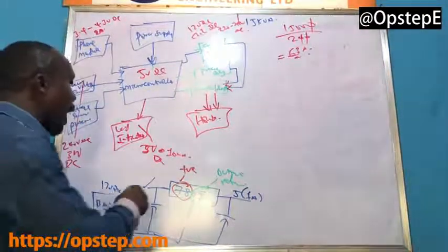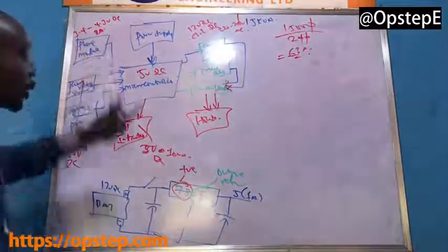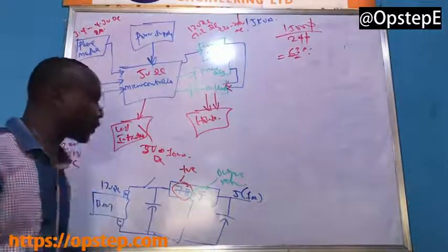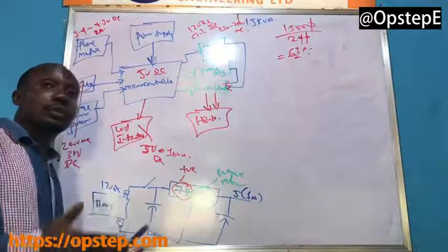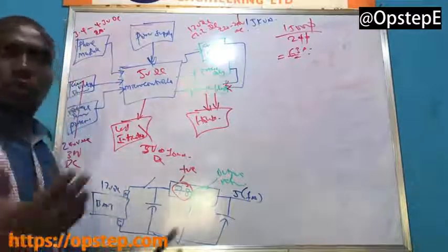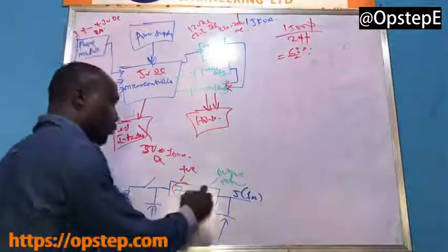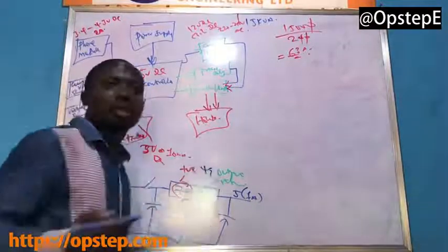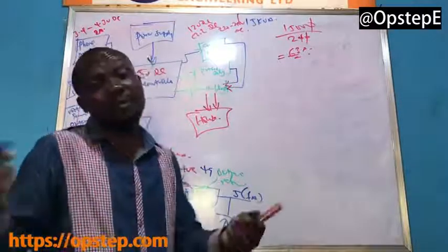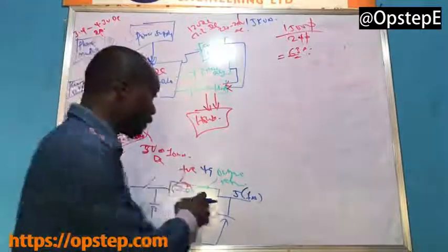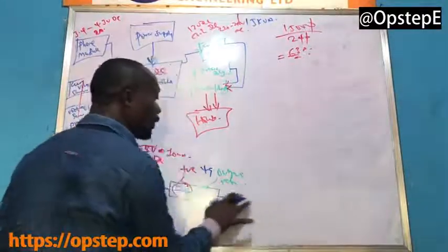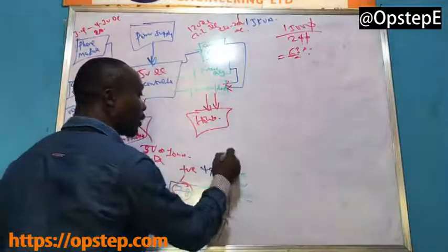Now, how then do you expect your 4G module to get voltage? Please look at this very crisply. You expect that your voltage regulator should supply you 5 volts. But of course, the voltage regulator is not going to supply you exactly 5 volts. It supplies maybe around 4.9 volts. Of course, the system can still work with 4.9 volts, even 4.7-something volts will do. What we did in this design is this: from this 5 volts, don't forget your 4.9 volts is here.